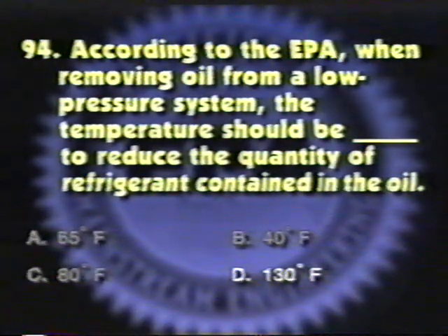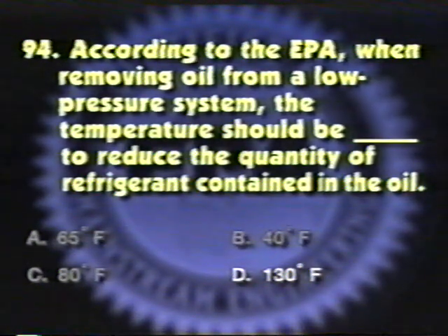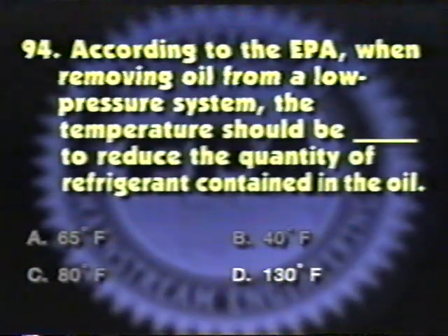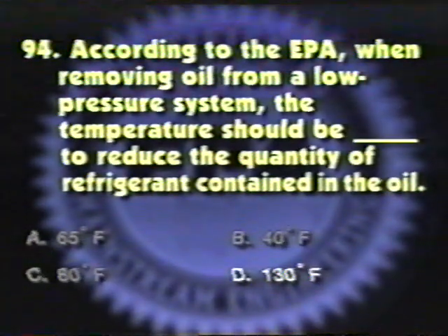The correct response is D. When removing oil from a low-pressure system, the EPA states the temperature should be 130 degrees Fahrenheit because less refrigerant will be contained in the oil at the higher temperature.